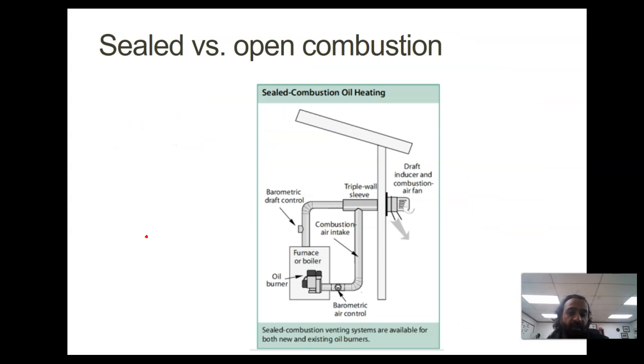Another term that you need to know is sealed versus open combustion. When we do open combustion, we're taking air from the house and throwing it outside. So probably you thought you need to introduce new air into the house. Otherwise, where is this boiler going to get air from, right? So to solve this problem, if you don't have a lot of incoming air into the house, you might need to do sealed combustion, where you take the air from the outside and you throw the combustion air to the outside. So this is a sealed design where you have the incoming air coming from the outside, from the same opening here, and you do the combustion and things get thrown outside.